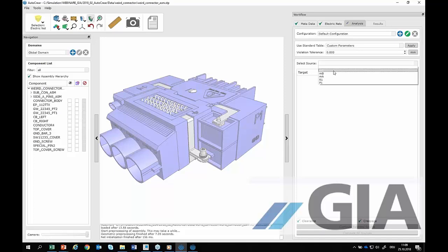This should be MA, and maybe between the net MA and R1, I want to key in manually the distances I have to fulfill. So it's maybe 10.5 from creepage, 6.4 from clearance, and the groove width is 1.5 millimeters.